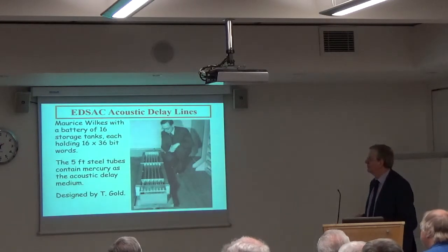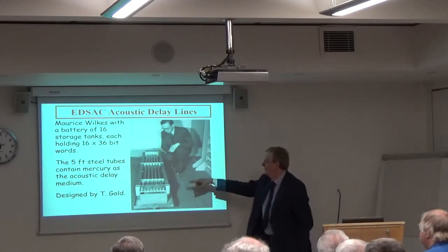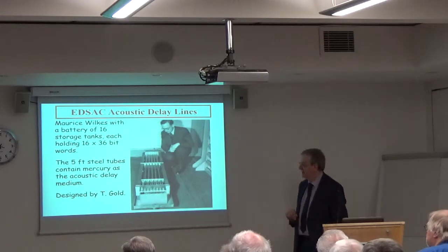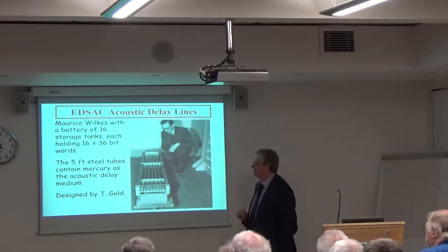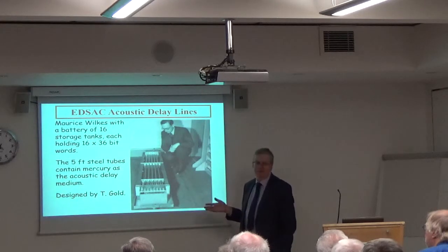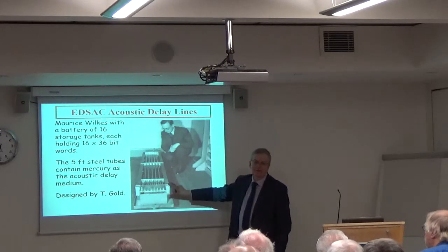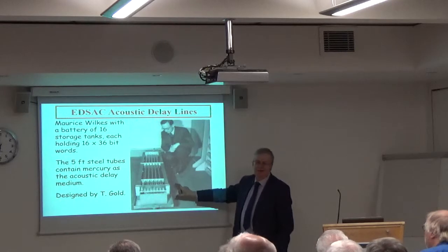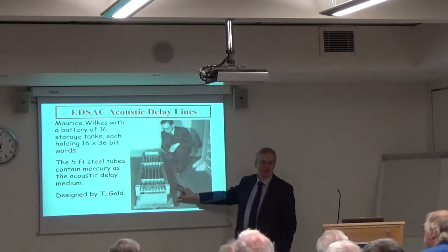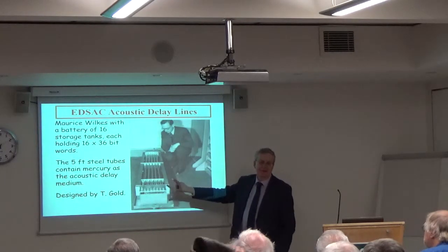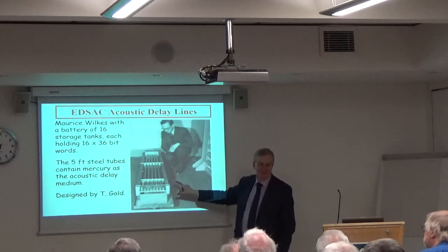So the memory of the original machine were mercury delay lines, tanks full of mercury with a piezoelectric crystal at each end, one to transmit and one to receive. I won't say very much more about the memory technology because there's a talk about that tomorrow. The key point is we felt we couldn't reproduce this. Everyone thinks it's health and safety. That's not actually an issue. When I investigated the health and safety requirements, it's an issue when you fill the tanks, but the Cavendish Physics Lab in Cambridge said they'd help you do that. They've got the appropriate facilities.